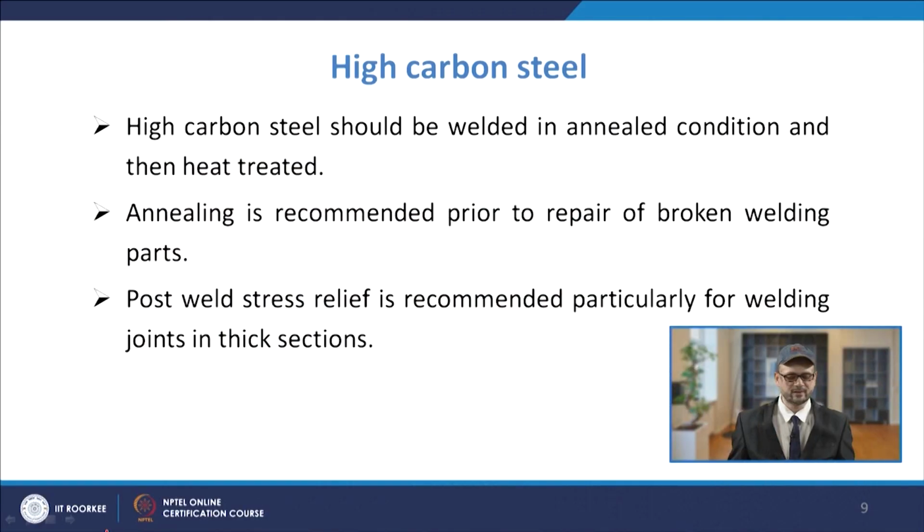Then post weld stress relief is recommended, particularly for thicker sections. In the thicker sections you need post weld stress relief, along with a proper welding procedure.